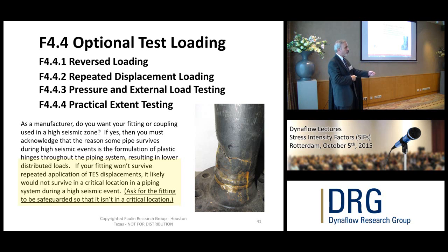So if they give you SIFs of 1 because they know they don't have a fatigue component, the problem today is in the code you're using 0.75 times I for your sustained load. And they are pressure sensitive to external loads. So when you put the design pressure on them, they won't carry the design load for straight pipe. If you put the design pressure on them and then put the bending moment on it that straight pipe will carry, they rupture. They are pressure sensitive. Their sustained load capacity is not a function of the capital I or the little i factor. When you put pressure on, they break.